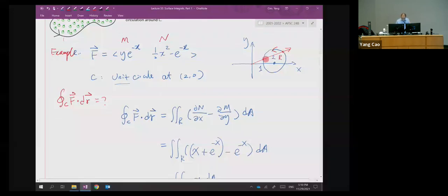But if you look at the current drawing here, is either r min or r max constant? If you draw arbitrary radial lines, the length for r min, the length for r max, or the length for the first contact and the second contact, neither of them is constant.